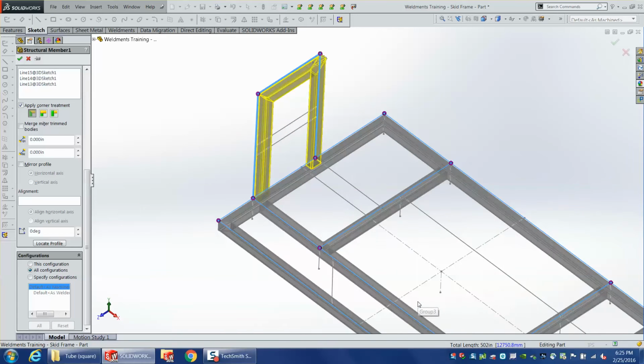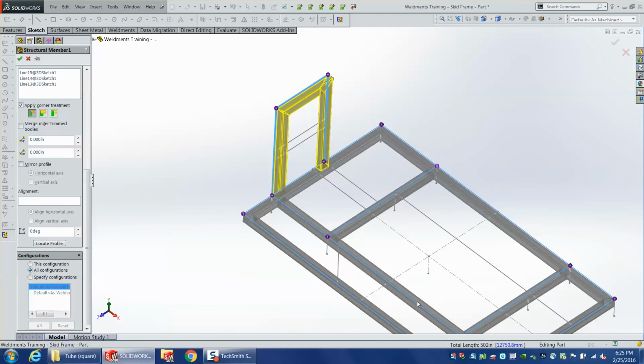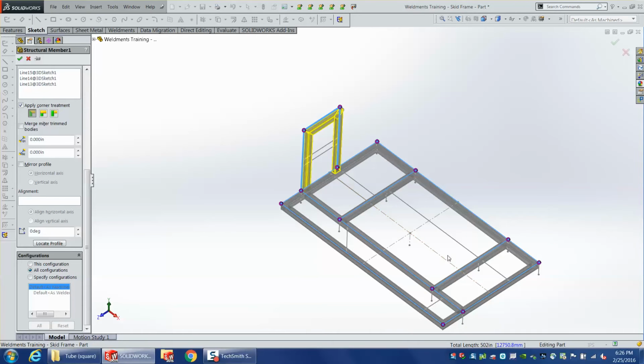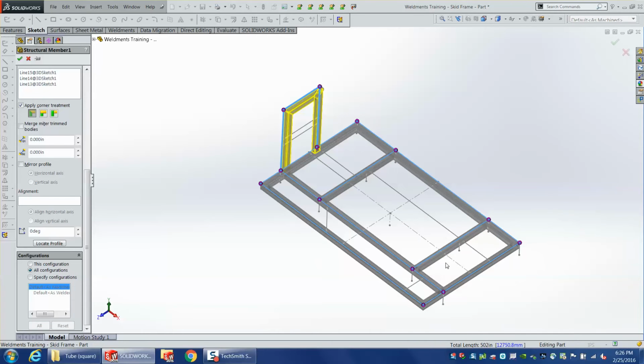So I recommend in creating your own or editing your own weldment profiles, which I'll show you in a minute, go in there and add as many points as you can think you ever might want to use, because they're useful. If you think a shaft, maybe you only show the center point of it if you were drawing just the profile, but if you're using it for weldments, you're going to want points on the sides of it, maybe in the corners and all over the place, because that may be your design intent at one time. I want this along the face of something.